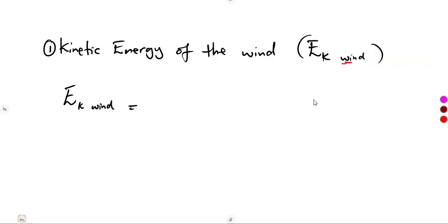So it follows that the kinetic energy of the wind can be determined. Guys, we do understand kinetic energy as half mv squared. It is the same calculation as we understand from our engineering science. So that is half mv squared, meaning we are considering the mass of the wind and the velocity of the wind. Kinetic energy is energy, which is measured in joules.